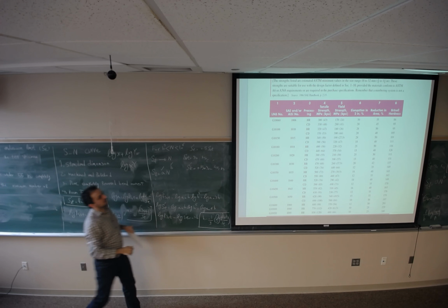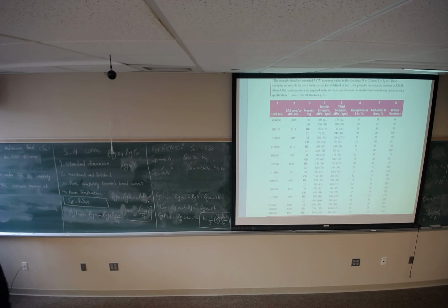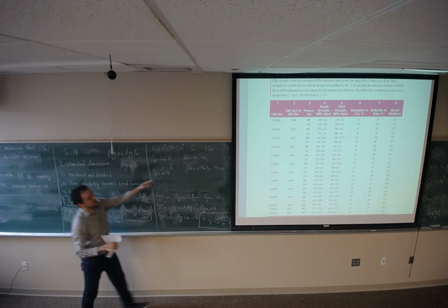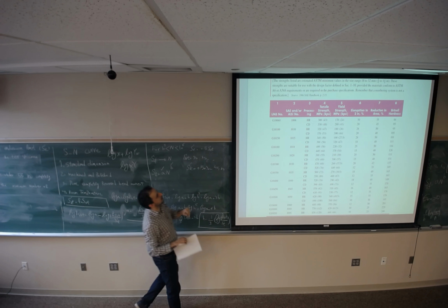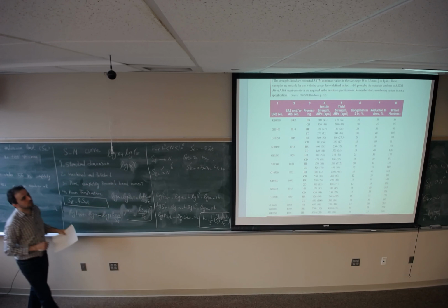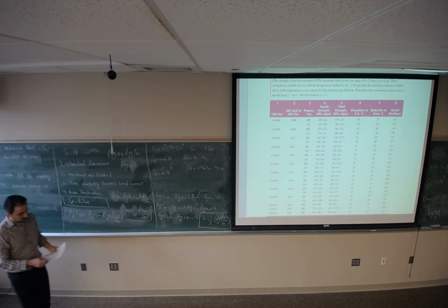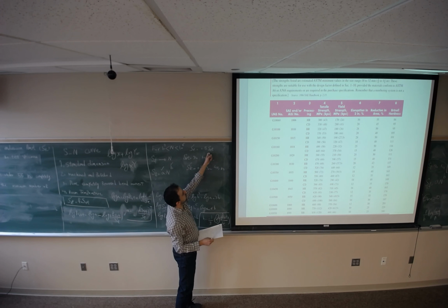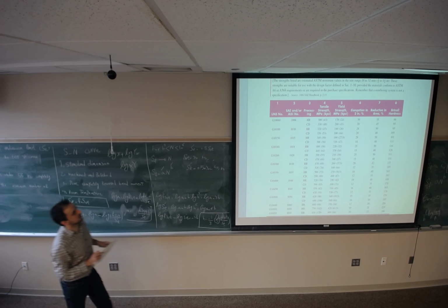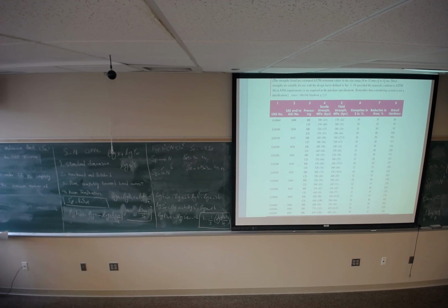The equation that I showed you has two versions. One is for MPa or megapascal, the SI unit, and the other one is the US unit, which is kpsi. So make sure that you are consistent when you are using this equation. So 45 kpsi is the knee point.